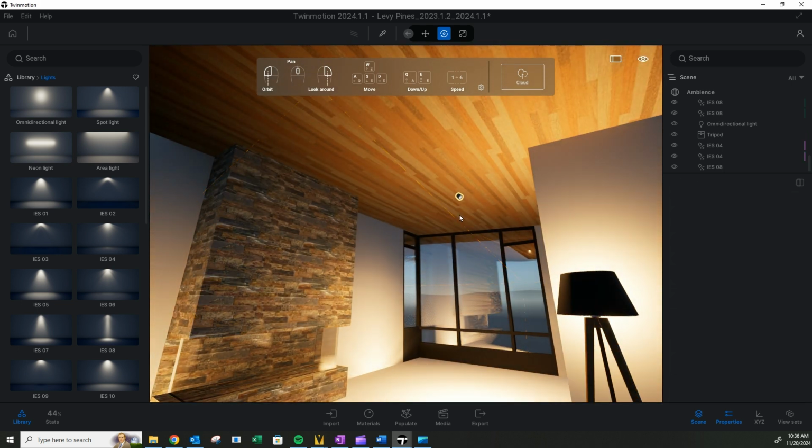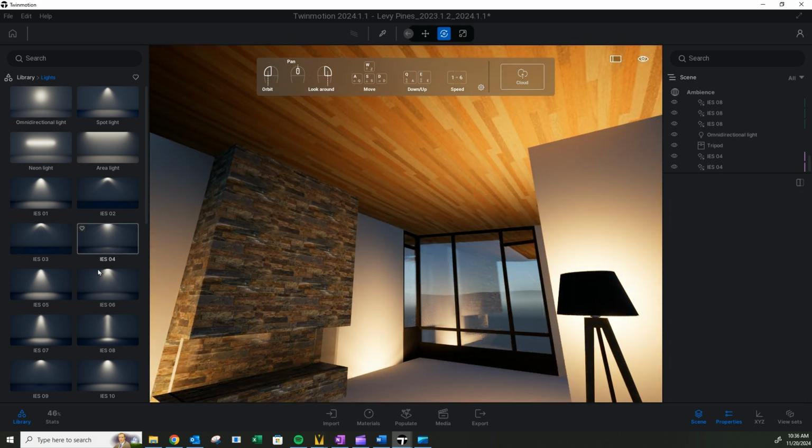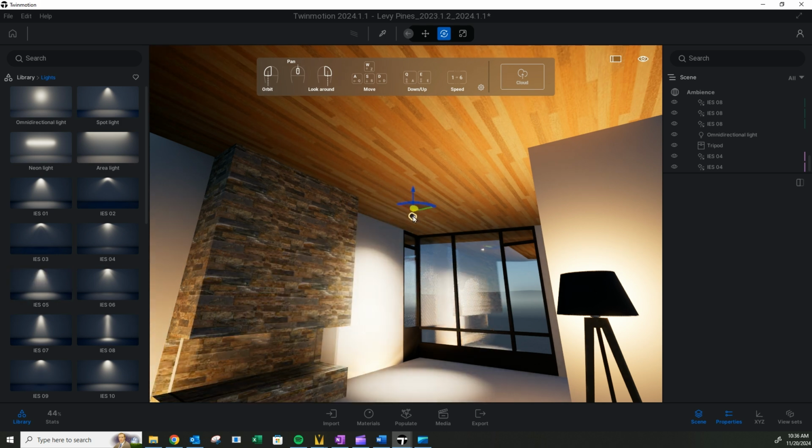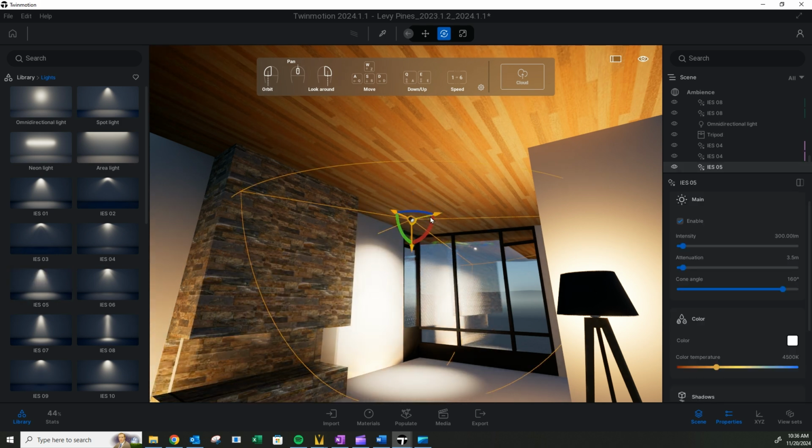There are lots of different ways to do it. If you have art lighting or just want to highlight the vertical surfaces, then you would pick an adjustable light and aim it towards the wall, and you place it a certain distance away, probably 2 to 4 feet if you're trying to wash the wall. And if you're trying to graze it, it depends on the light, but probably 6 to 12 inches from the wall.